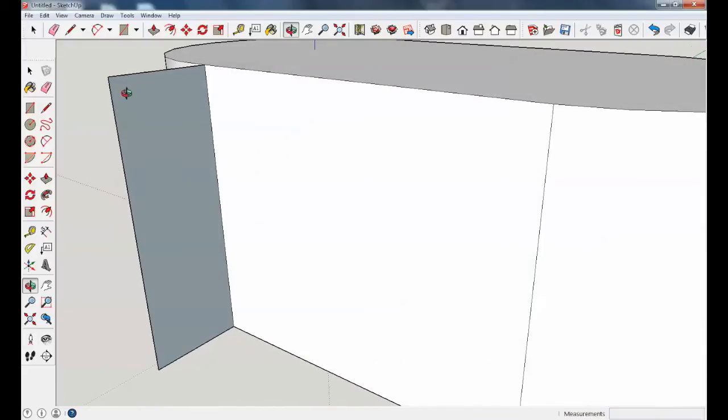For the next bit, you will need to select the Arcs tool. Now the default selection for this is the tool that we need. However, if you want to go on the drop down menu, it is the 2-point arc. So I'm going to select that there, and now I'm going to guide my mouse so it snaps to the green endpoint that we used earlier. Single click here, and now drag out at roughly a 45 degrees angle, and then click again.